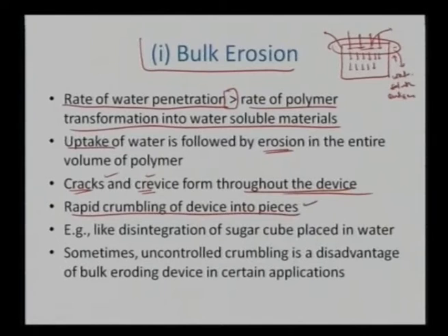of the device into pieces, because as soon as we have a particular polymer and we start seeing the cracks, and this process is a little slower than the water uptake, we see rapid crumbling because water is now sieved throughout the bulk of the material, and that is what leads to the overall sudden failure or sudden crumbling of the device into pieces. So it can also be seen more like the dissolution of a sugar cube. If you keep a sugar cube in water, it will start crumbling rapidly or suddenly.